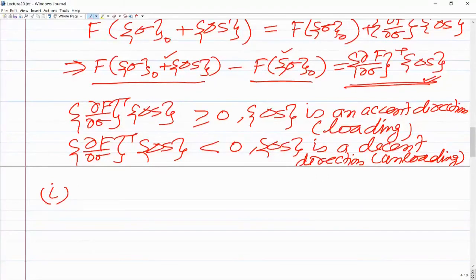You have to store all the components of stress at all Gauss points of each element. You have to store this status variable. You have to store the plastic strain, epsilon equivalent P. You have to store the plastic work. You have to store the back stress. So all those quantities have to be stored. Compared to an elastic analysis, you have to store so many variables, so that from the previous step or previous iteration, you have those values available, and then you can update them.